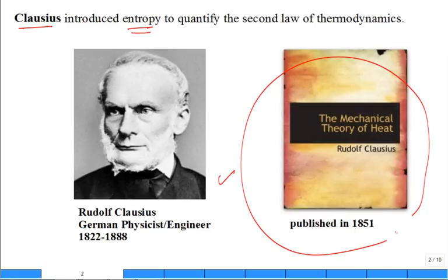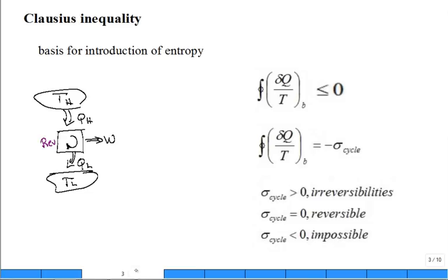I don't know, it's a property. What's it defined as? Well, it's hard. But it's going to come out of this Clausius inequality. So what's the inequality? It says that the sum of the heat transfer into the system, if it's negative, then it's out of the system, divided by the boundary temperature for the entire cycle is less than or equal to 0. So they make it an equality by making it equal to something that's negative, and this is the strength of that inequality.